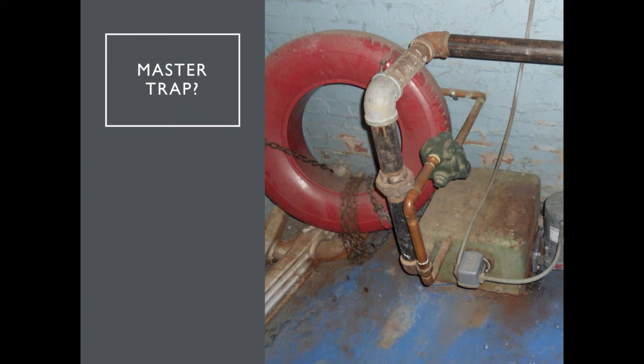Typically, we see designers or engineers size those for between 5 to 7 psi. So if we try to run at 2 psi on a commercial building like that, it's not sufficient, and they don't get enough heat from the steam to water heat exchangers.